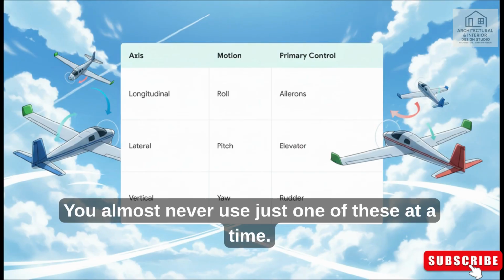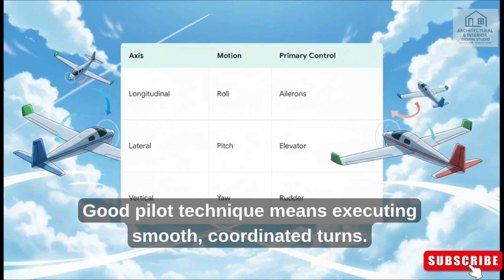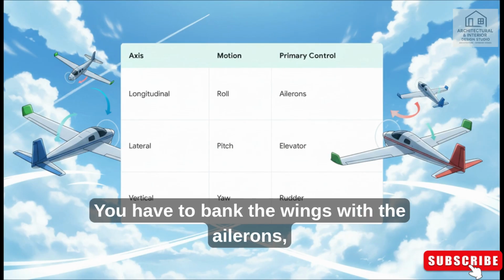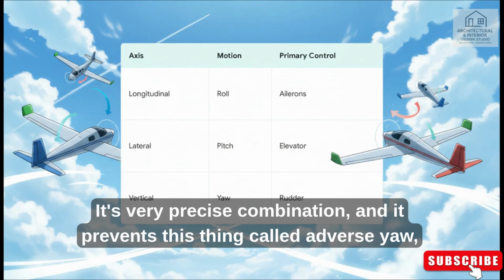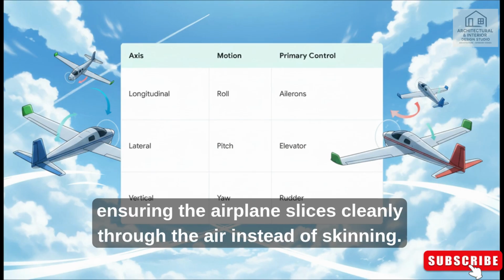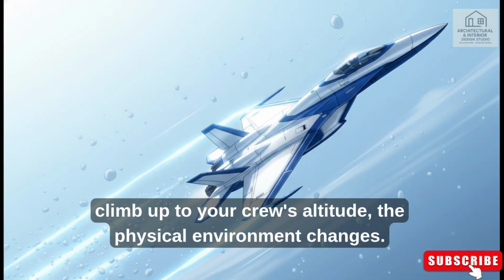But here's the trick. You almost never use just one of these at a time. Good pilot technique means executing smooth, coordinated turns. You have to bank the wings with the ailerons while simultaneously applying rudder pressure. It's a very precise combination, and it prevents this thing called adverse yaw, ensuring the airplane slices cleanly through the air instead of skidding.